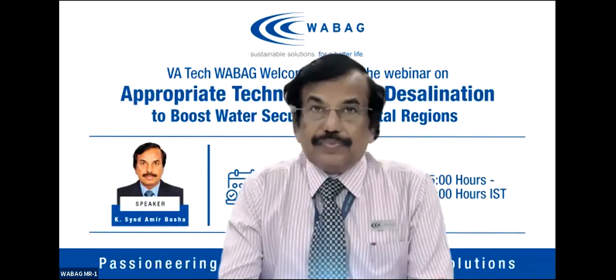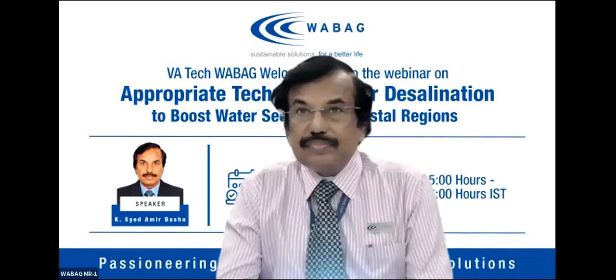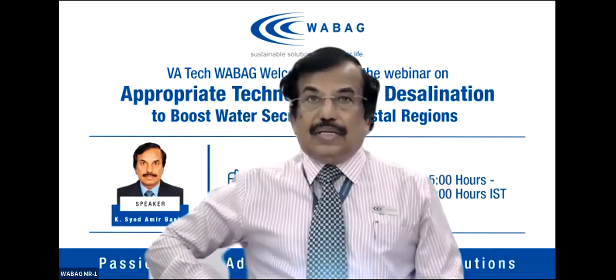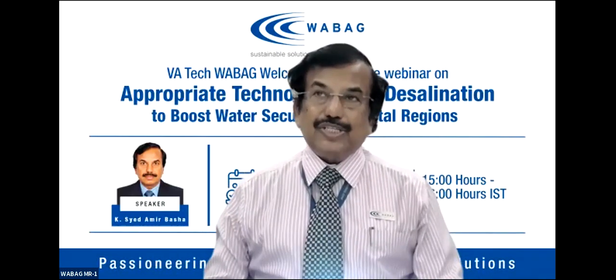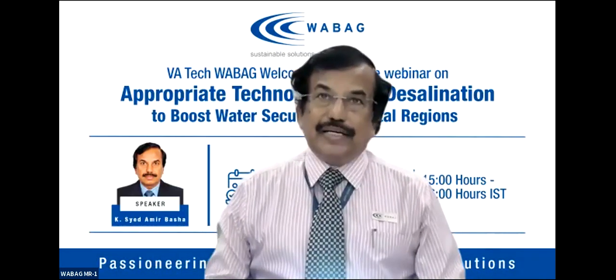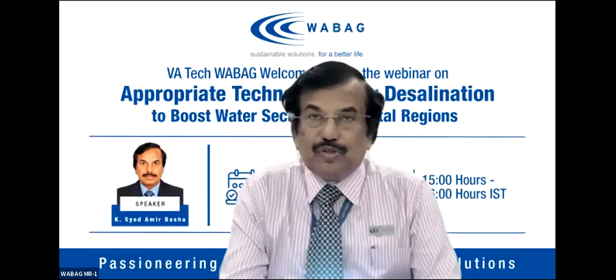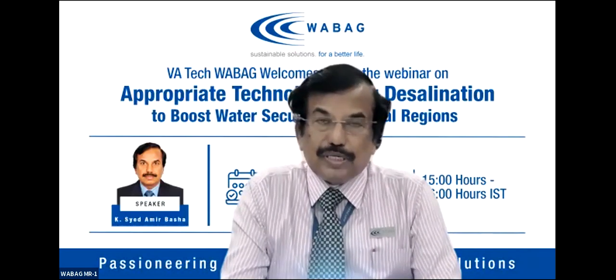Another question from Mr. Anand Raj. What are the disposal methods of sludge which are removed during the pre-treatment? Actually, the sludge is concentrated and passed through the centrifuge, and by passing through the centrifuge, you are able to increase the sludge consistency, remove it almost, and dispose it through trucks.